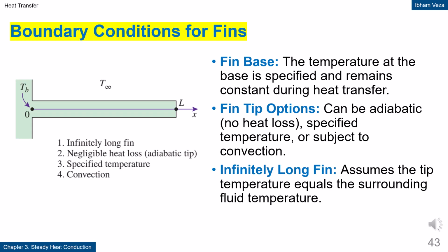Boundary conditions for fins. The temperature at the fin base is usually specified and kept constant. The fin tip condition can be adiabatic, at a specified temperature, or subject to convection. In the assumption of an infinitely long fin, the tip temperature is considered equal to the surrounding fluid temperature. The choice of boundary condition strongly affects the temperature profile solution. Therefore, the model must match the real physical condition.